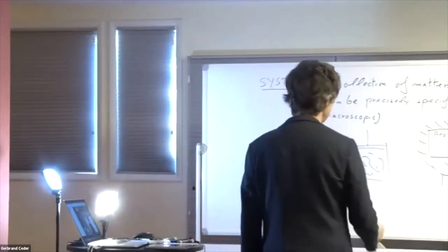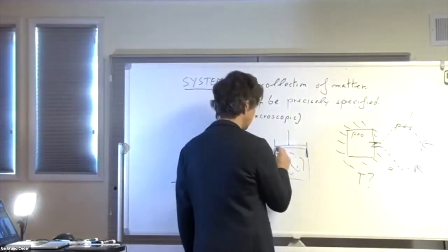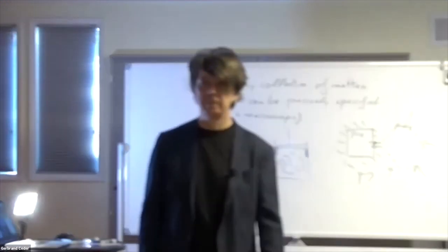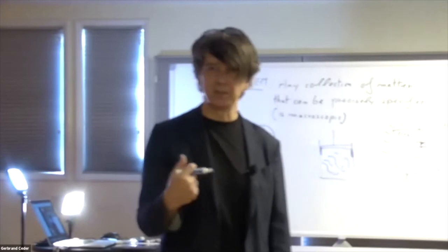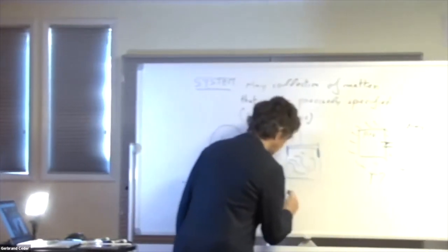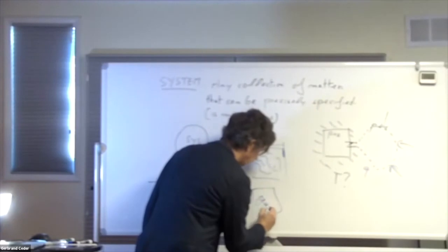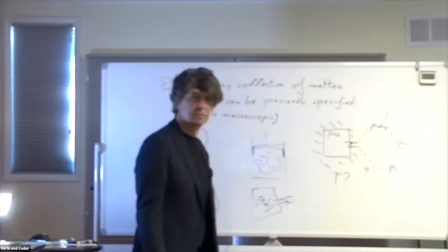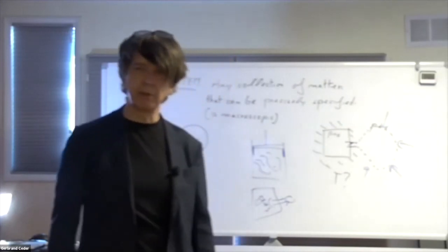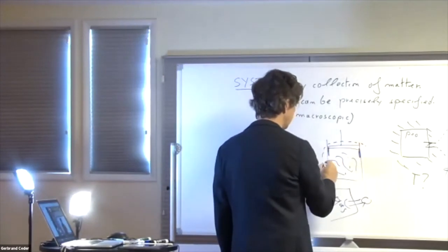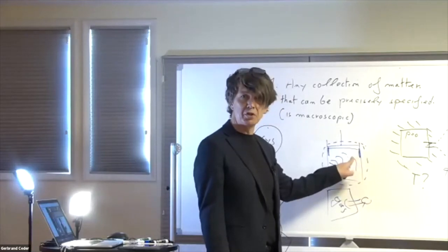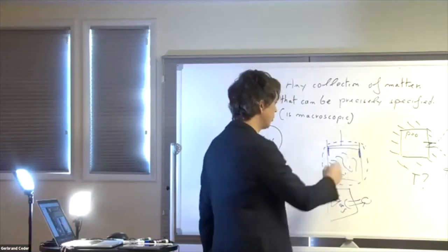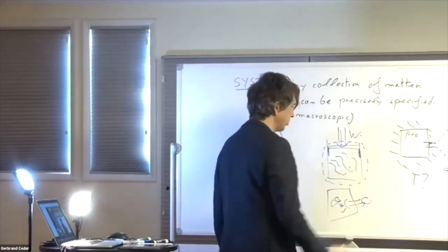Imagine that the piston has friction here, right? That generates heat. If the gas is the system, then I only have heat coming into the system, because the gas doesn't see the friction. If the whole piston is the system, then the heat flow is internal, so it's not coming across the boundaries. Then the only thing into the system is the work by which I push the piston down.